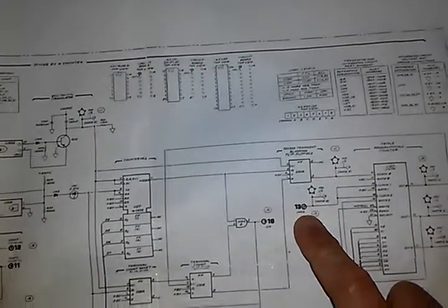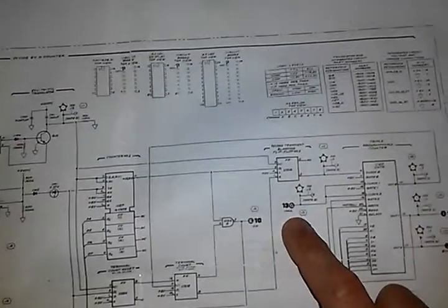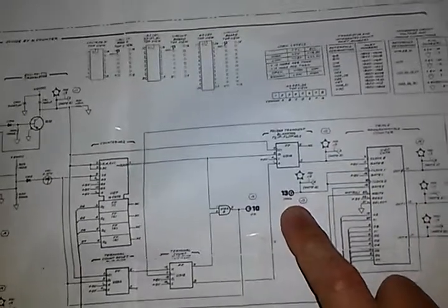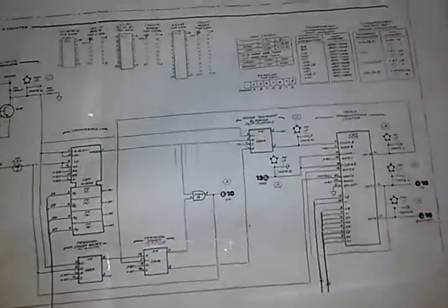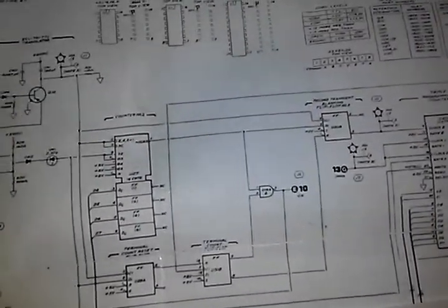There's an oven-controlled oscillator source or a regular crystal source. Mine has the oven-controlled oscillator option. And that becomes the time-base reference. So, of course, I'm sure you all know how PLLs work. It compares the two in the phase comparator, and then you have a charge pump,